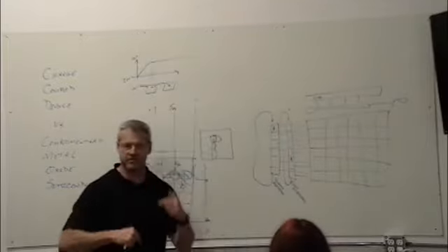And I say, no, I want to change my integration time. I want it to be a lot shorter, so I'll make that one a 1. So it's only a 1-line integration time. And so if I'm stepping them out 1,000 lines per second, well, that's a millisecond integration time. If I push it all the way to the other end, it's a 1-second integration time.